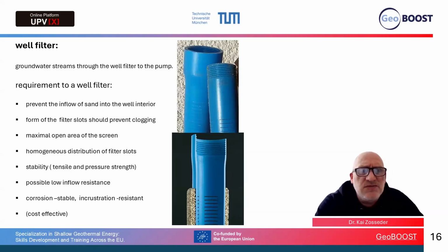So groundwater streams through the well filter to the pump and into our well. There are some requirements to a well filter. Of course, it should prevent an inflow of sand into the well interior. It should also prevent clogging effects, so the filter slots should have the right size.